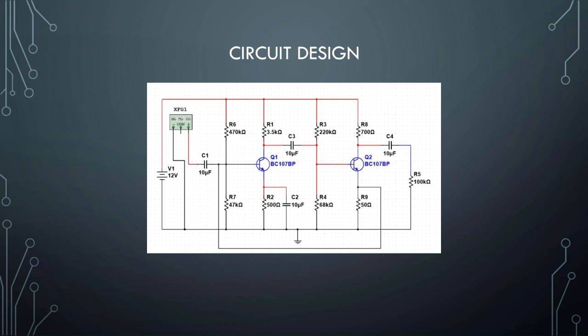For transistor operation, the input signal current flows through the base emitter junction from Q1 to Q2. Due to the common base configuration, the collector current is nearly equal to the emitter current.